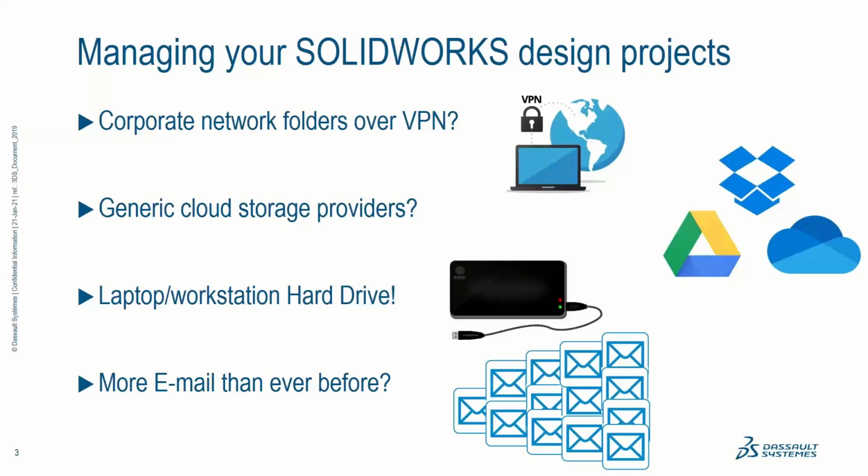Generic cloud storage solutions can offer a bit more flexibility, but they don't understand the interdependencies that can exist between SolidWorks files. So if you move files around between different folders outside of SolidWorks, you can easily get yourself into a bit of a mess, where assemblies and drawings, for example, suddenly can't find their dependent parts when you attempt to open them, which is never good.